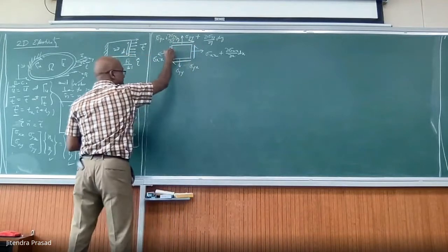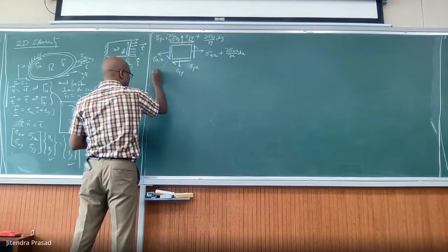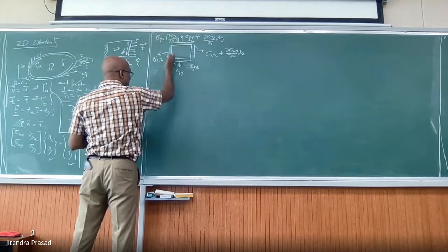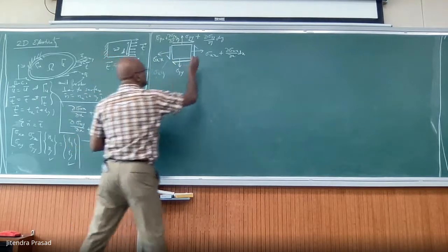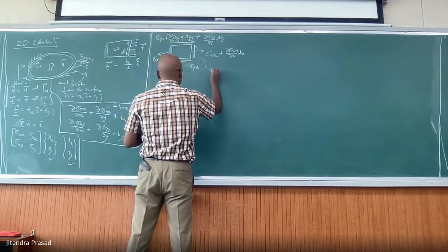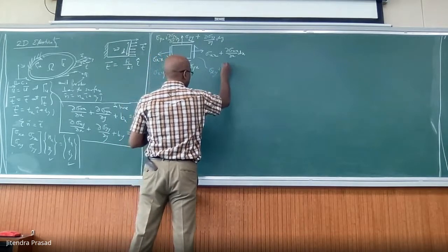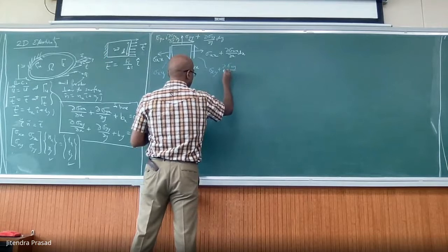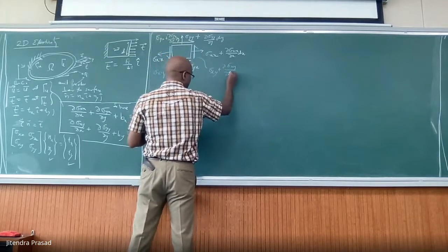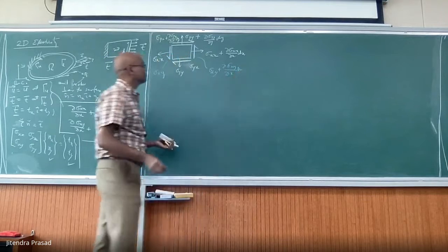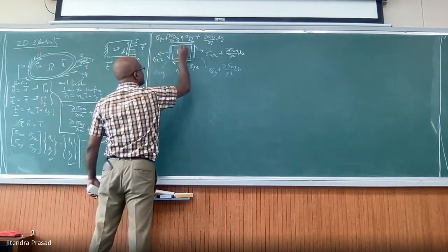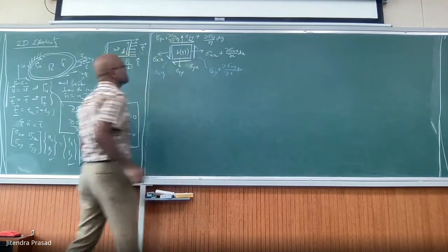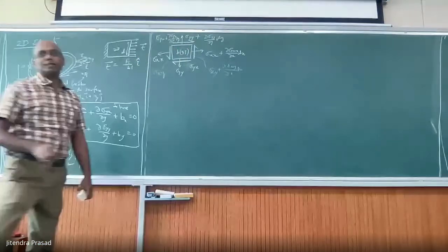Similarly, this one is the stress on x face in y direction, sigma xy plus del sigma xy over del x dx. And of course we had the body force bxy within it.